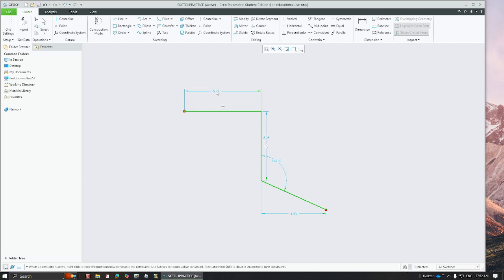So you can go on to modify these dimensions. Now the way with Creo is the minimum dimensions required to completely define your geometry will always be present in your sketch. Now sometimes these dimensions may not be to your liking, and you will be able to create other dimensions that you want. So the way to do that is from here, and the way to create new additional constraints is from here. We'll learn about more of these slowly as we experiment with more of these drawing entities.